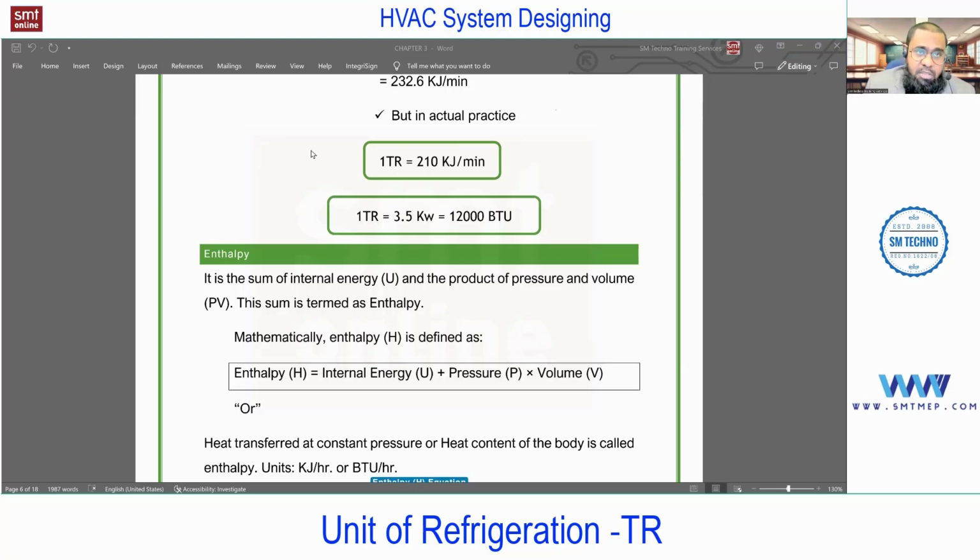In the case of a chiller, the case is different. The chiller starts at 0.7. Again, in chillers we have high-class chillers or standard chillers, etc., so that range will vary. Yes, sir. For coordination, 1.2 to 1.4. Yeah, because the electrical engineer is always asking about the electrical load of the HVAC. You can consider in between 1.2 to 1.4 for a DX system. For a chilled water system, it is going to be different.